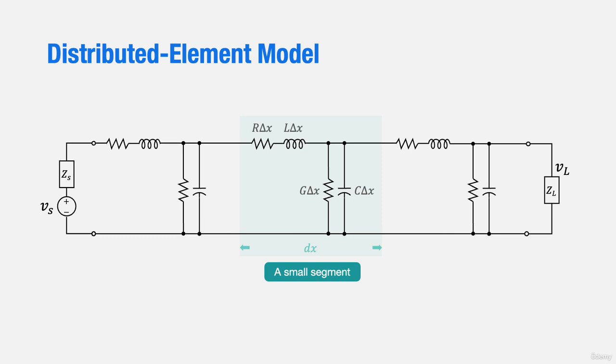We'll use the distributed circuit model, or RLGC model, which takes into account the losses and self-inductance on a non-ideal line. There are dielectric losses between the live wire and ground, and there are capacitive effects in between as well. To learn about different types of transmission lines, we can refer to textbooks on electromagnetism or microwave engineering. Understanding their characteristics requires determining the parameters of different types of transmission lines through electromagnetic field theory.